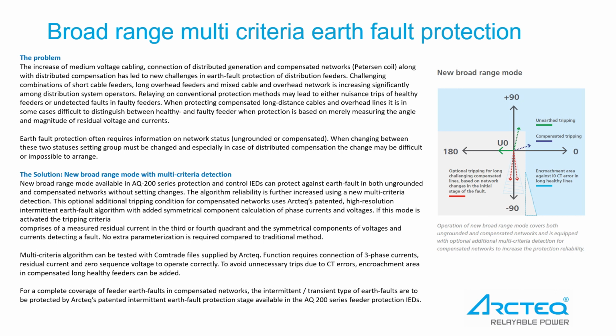The algorithm reliability is further increased using a new multi-criteria detection. This optional additional tripping condition for compensated networks uses Arcteq's patented high-resolution intermittent earth fault algorithm with added symmetrical component calculations of phase currents and voltages.